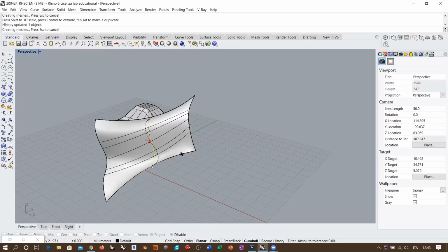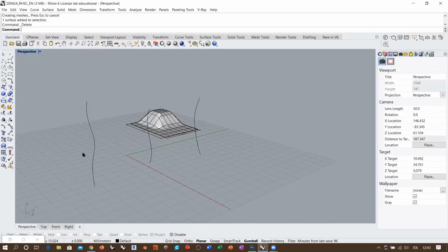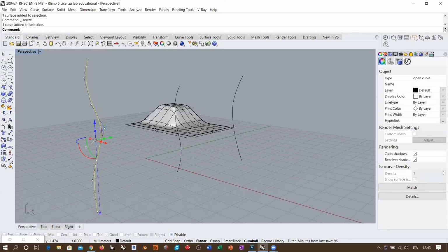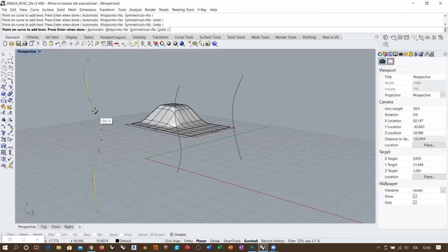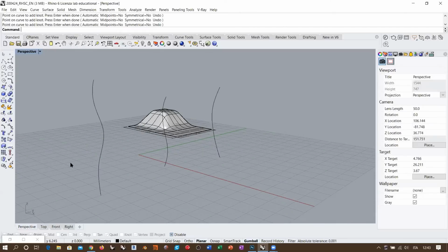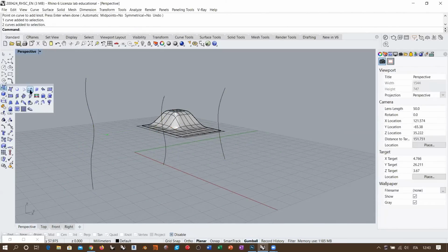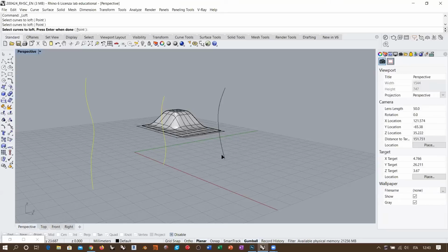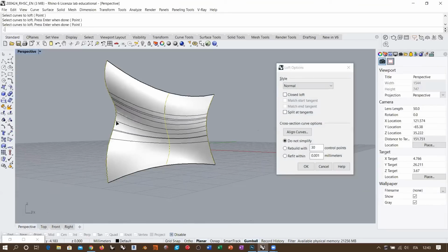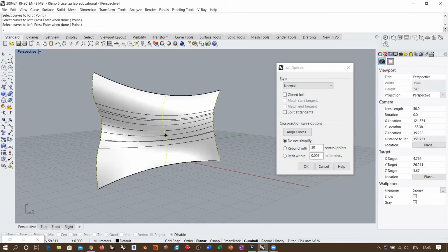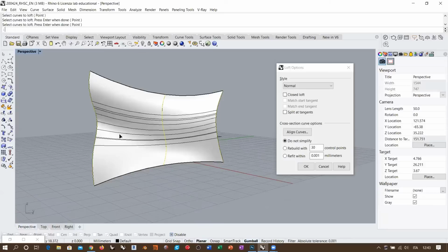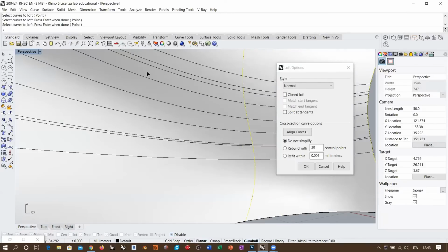Oh, by the way, what I want to do is also adjust or create some more complex topology by inserting knots along this curve, for example, in this area, okay, in the central area. So this topology is way more complex than these two here. So we know that if I execute the loft command like this, then I get more isocurves, more knot spans concentrated in this area. Also, very concentrated knot spans like this and this one.